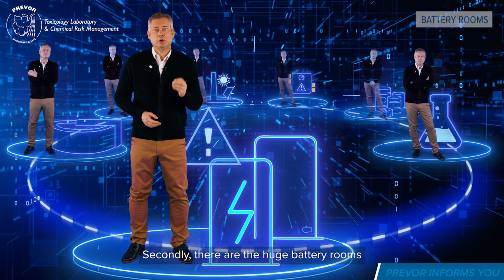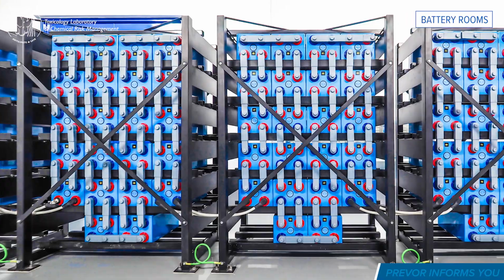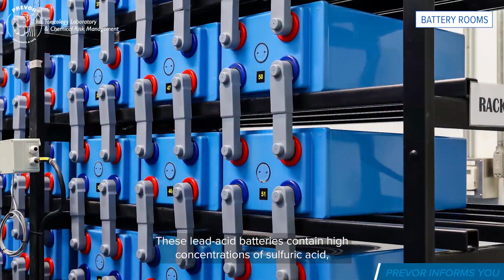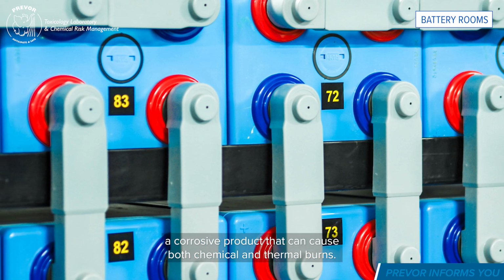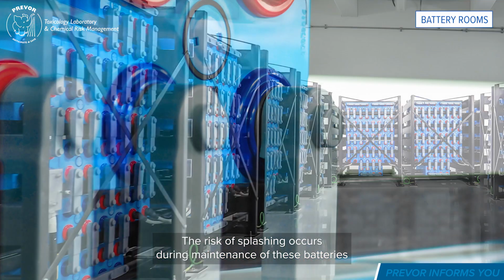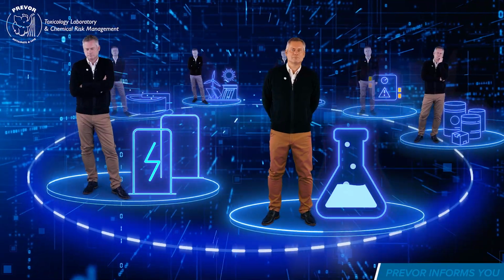Secondly, there are the huge battery rooms which provide electricity in case of failure. These lead-acid batteries contain high concentrations of sulfuric acid, a corrosive product that can cause both chemical and thermal burns. The risk of splashing occurs during maintenance of these batteries when they are recharged with distilled water.